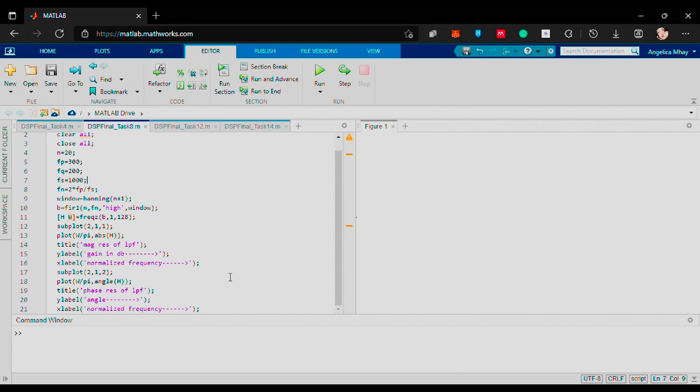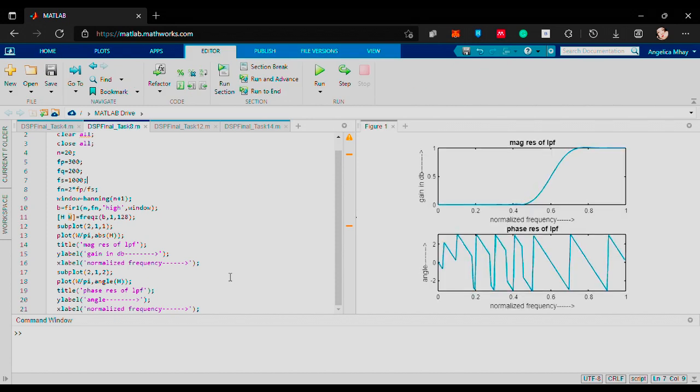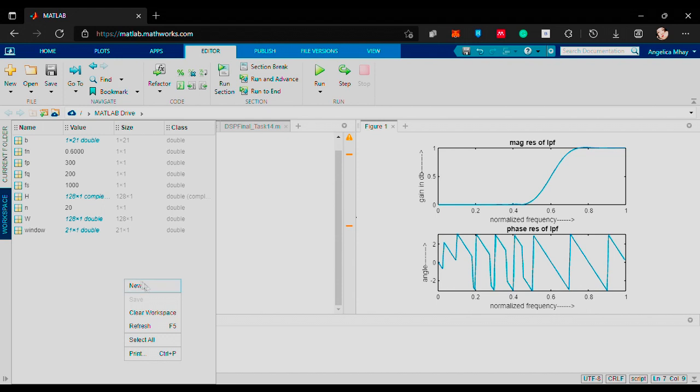This task actually gave us students a chance to practice implementing a non-recursive digital filter, and as we can see in this activity, it is a digital filter with a limited impulse response. So this is the magnitude response and this is the phase response of the Hanning window. And for the workspace, these are the values that are in the figure as well.